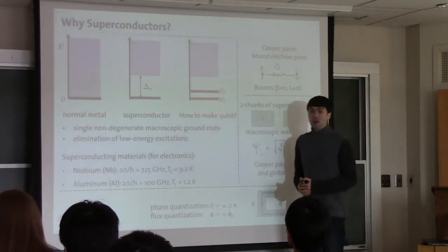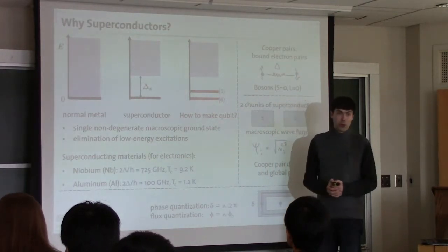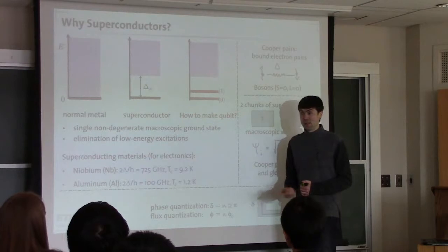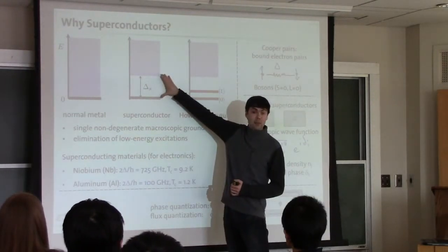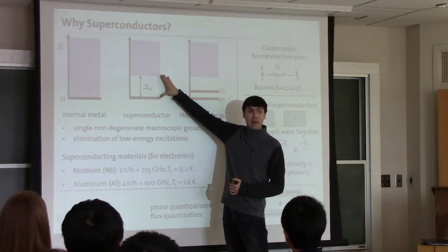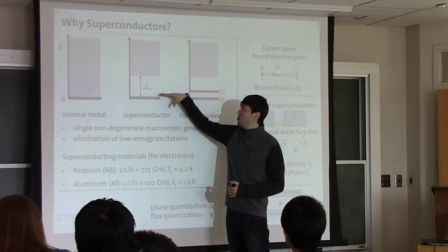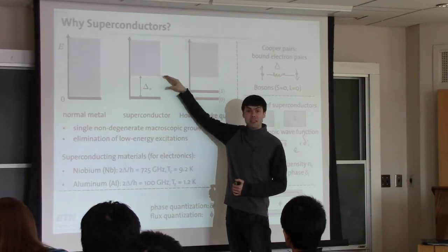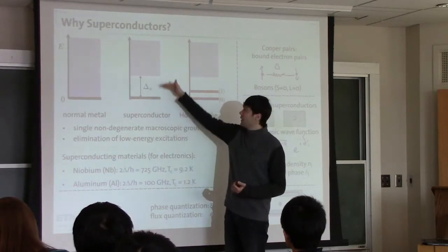Okay, there is a very good motivation to indeed use superconductors to go to the quantum limit of electrical circuits. And the primary reason is the superconducting gap. Remember the gap around the Fermi level ensures that there are no intermediate levels, excitations, in a piece of superconductor up to the gap.